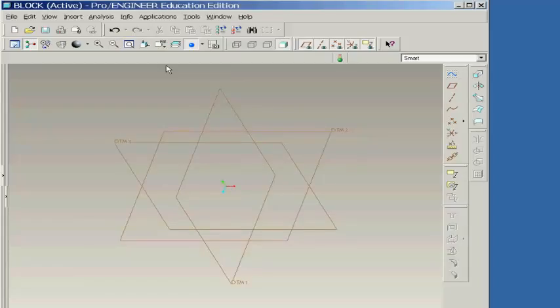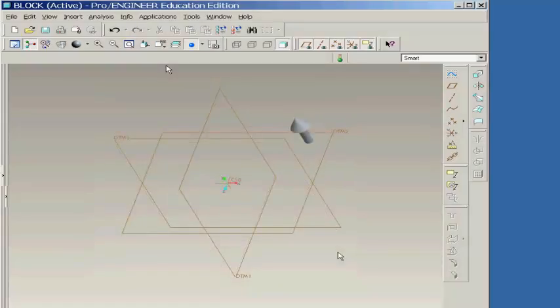Let's take another brief look at how the concept of orientation with datum planes can be envisioned. Pro E will often reposition a view based on the direction in which the positive side of a datum plane is pointing. A normal vector emanating from the positive side of one of the datum planes, as shown here, illustrates the direction that the datum plane is pointing.